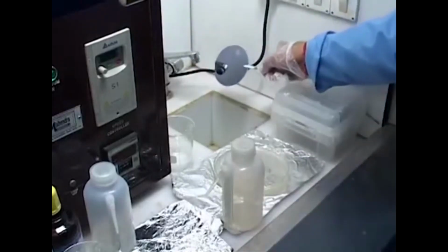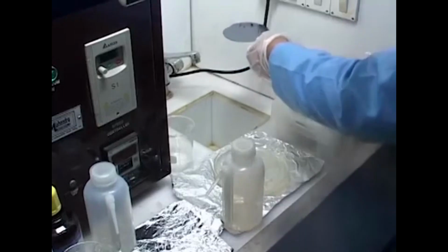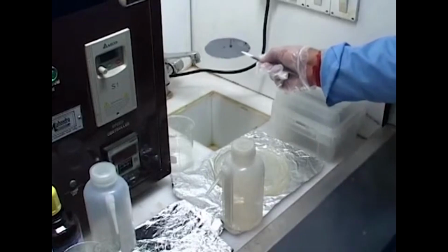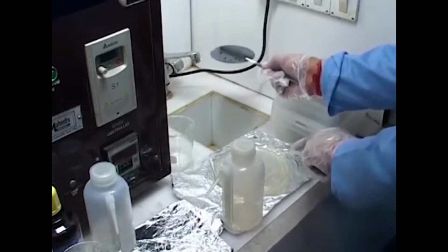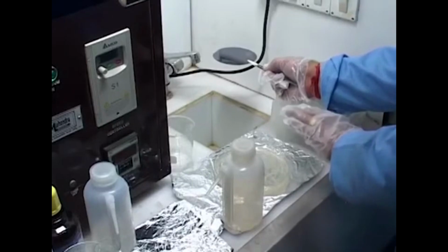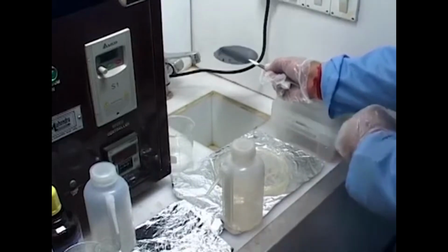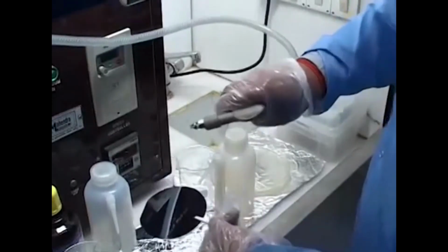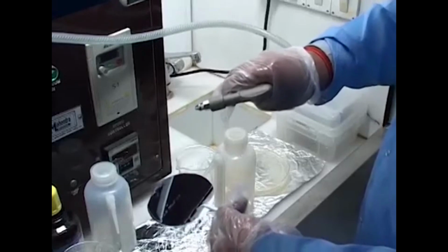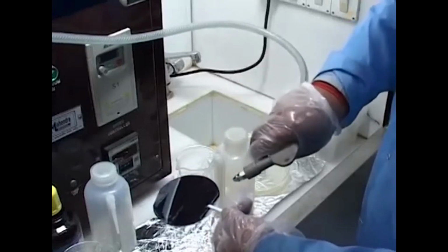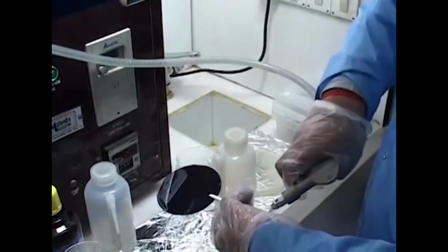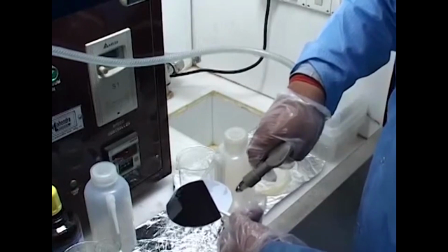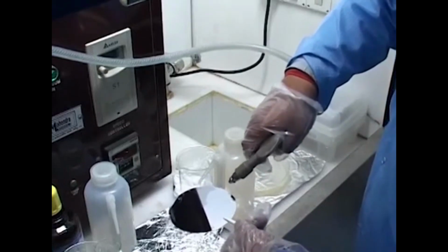So once this is totally clean, we need to now use the compressed air to dry this particular wafer. But before doing that, we need to take care that the acid, etc., which is actually kept in open, needs to be kept away, so that there is no squirting of the acid in general. So now you take it. So this is basically an air nozzle. It actually sends in compressed air, and what we are going to do is to actually slowly use this nozzle to clean off the surface water, as you can see here, slowly from the surface.